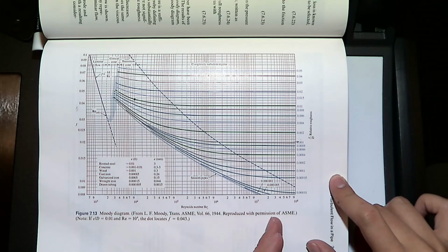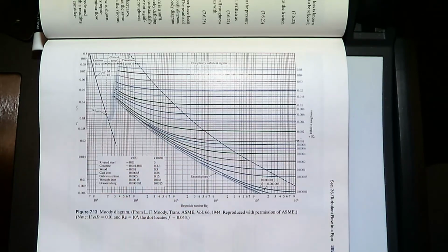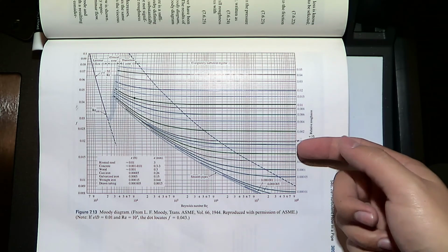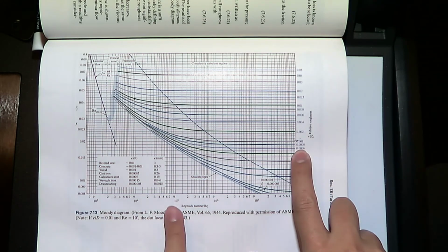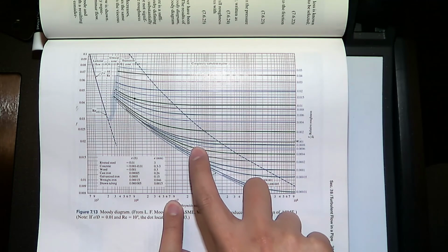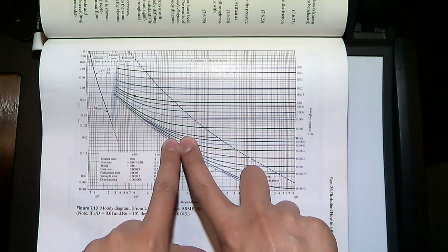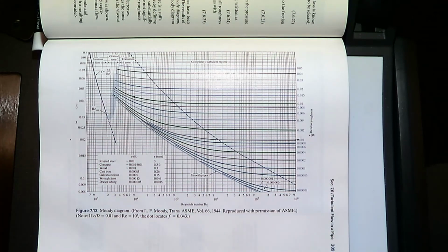So why are they curved? Because the Reynolds number, right, will then tell us where the Reynolds number intersects with that line. That is the friction factor that we're going to use. And we're going to do some examples, so don't worry, I'm not going to just say this and throw you to the wolves here. But essentially, if you know your relative roughness and you know your Reynolds number, you can move following your relative roughness line until you have an intersection with your Reynolds number. And from there, it's a straight shot to the left and you get your friction factor, okay?